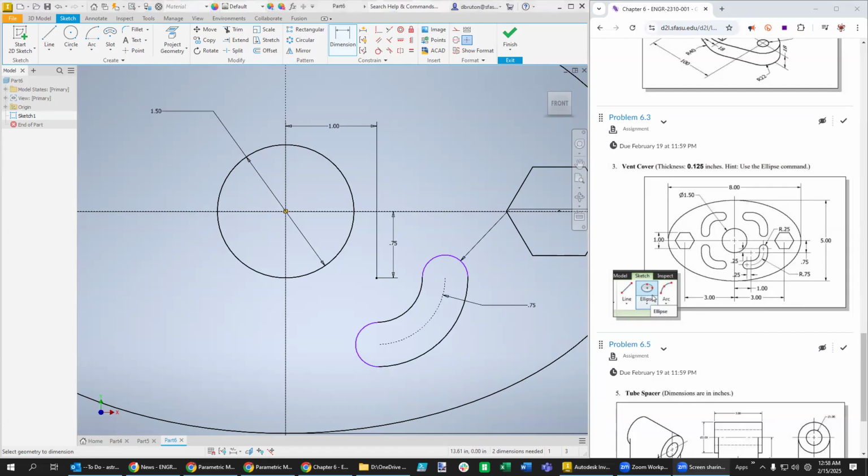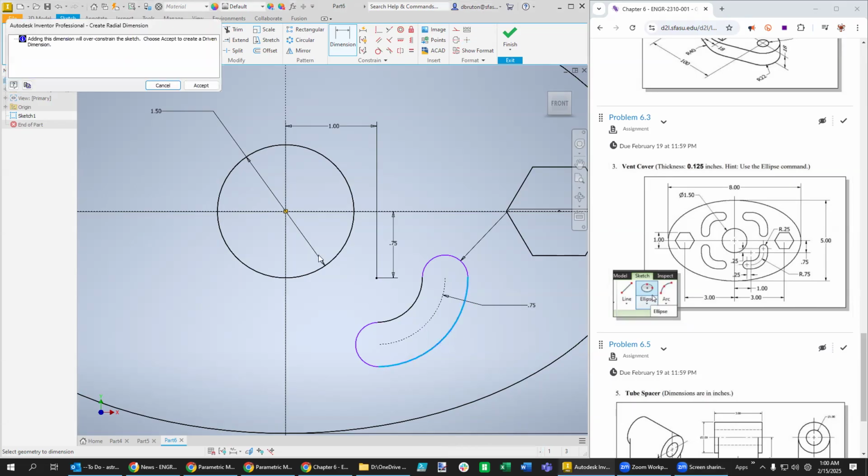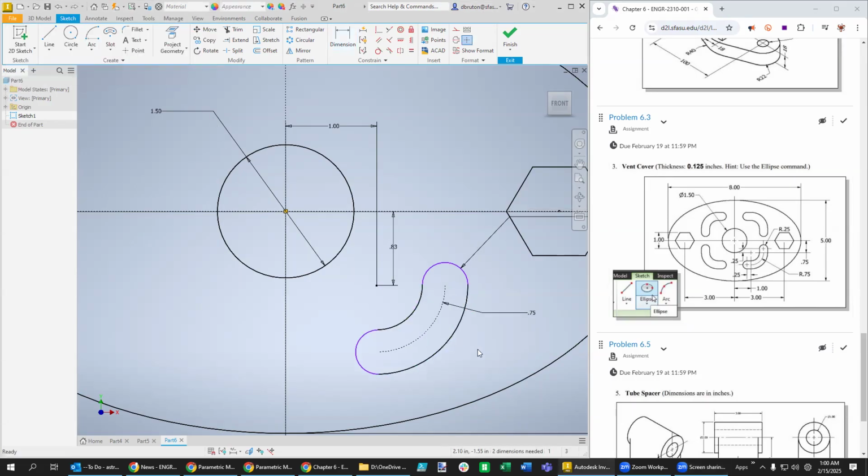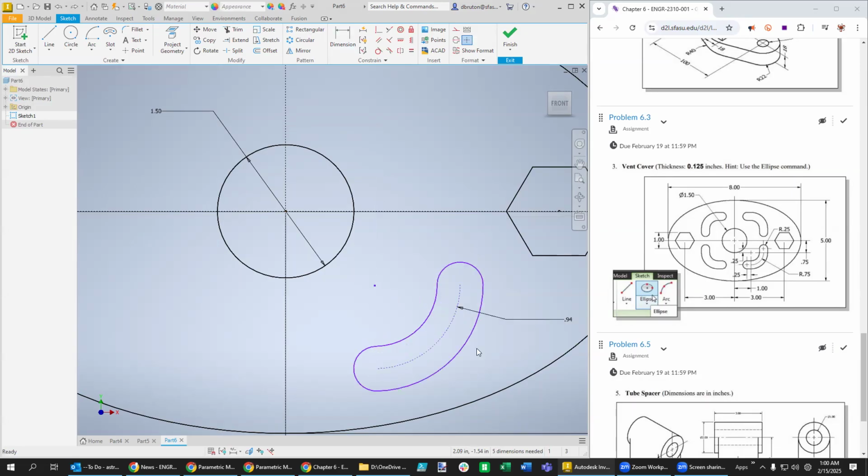Got to zero in on that a bit. And you begin to see after closer inspection that this is really a straight line before you hit the arc here. That straight line from here to here has a distance of 1/4 of an inch. So it's not going to be the slot tool after all. So let's hit Control Z on this one, remove all of that stuff, and start over with at least some kind of point out there in space that we could use. Or we could just draw